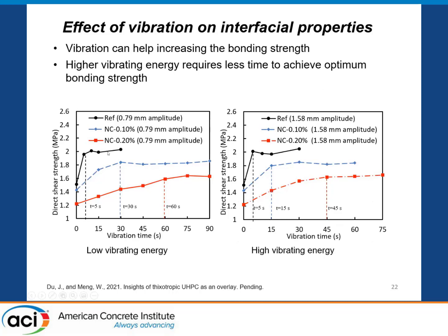But for UHPC with different thixotropy, you will need a different vibration time to achieve the optimum bonding strength. And if you want to shorten the time to reach the optimum bonding strength, then you will need to apply higher vibration energy.